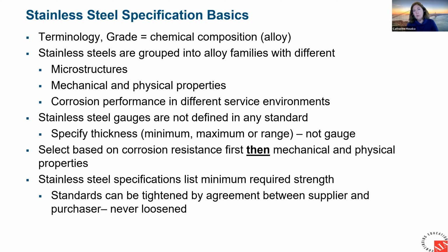We also, because stainless steel is not going to be protected, always start with corrosion resistance. And then once we see what's available at the level of corrosion resistance that we need for the service environment, look at the mechanical and physical properties and other considerations.